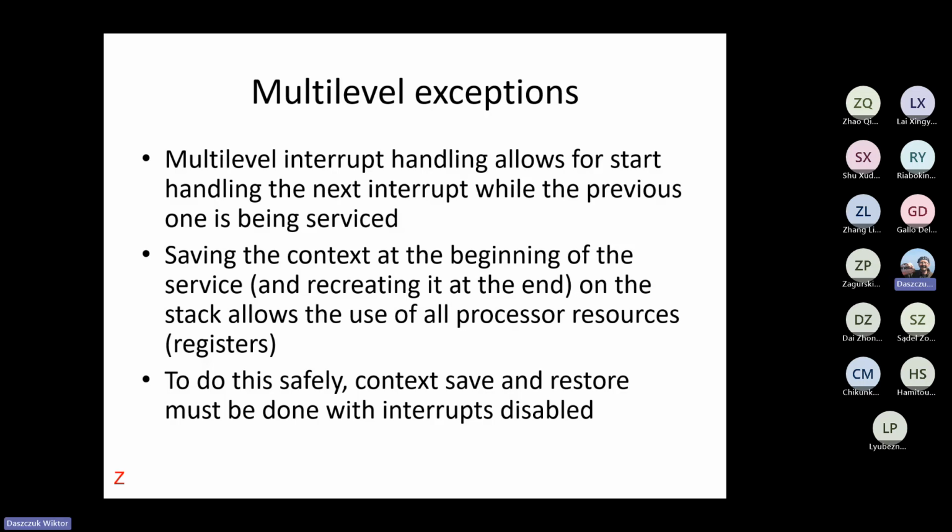That's why at the end of storing the state of the task, we had the enable interrupts instruction. When the task state is successfully stored, the interrupt handler enables interrupts to let interrupts with higher priorities be served.